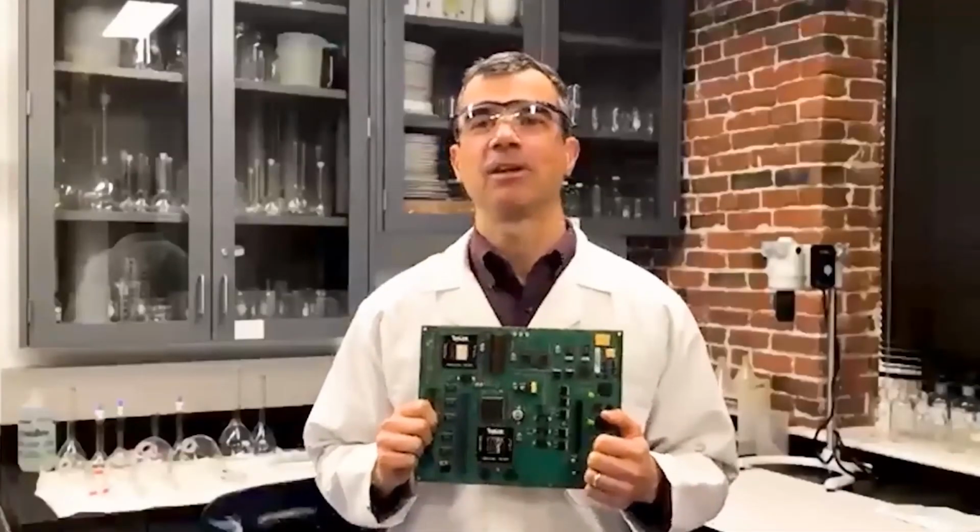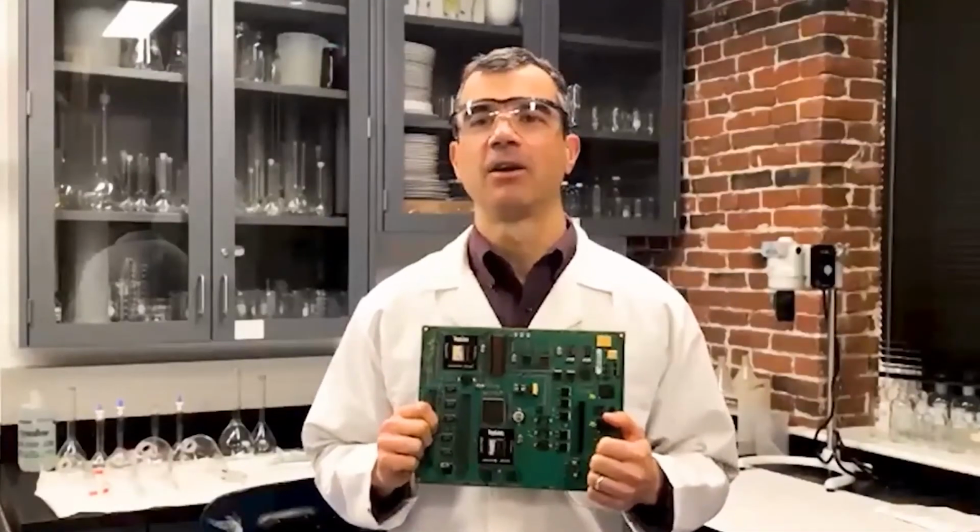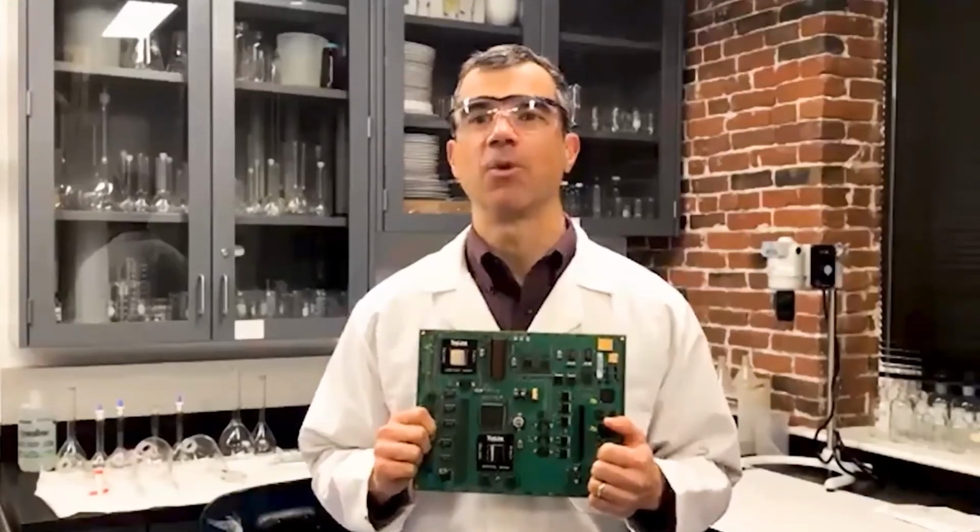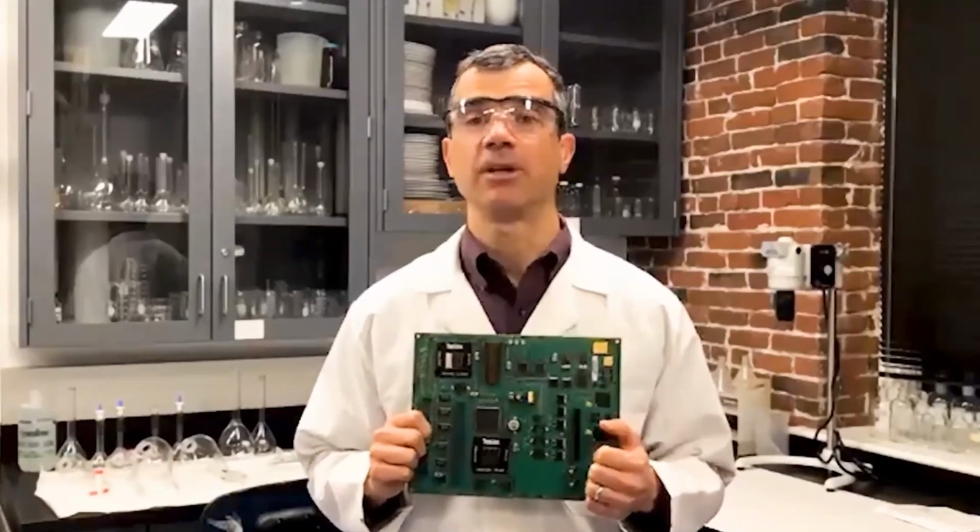With the test protocols, you also need to determine if any statistical significance is required. Do you need to do replicates? Do you need to do design of experiments or analysis of variance? What type of statistical tools and significance are needed for your results so that there is confidence that you're meeting your objectives? Here is an example of a test vehicle that was designed for trying to find a replacement for lead in solder for the electronics industry.